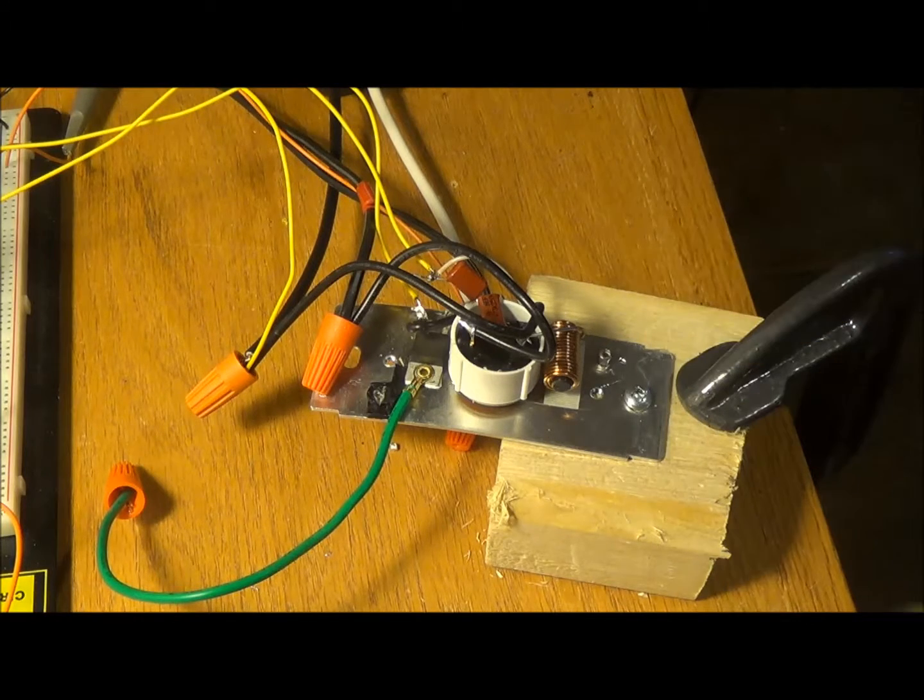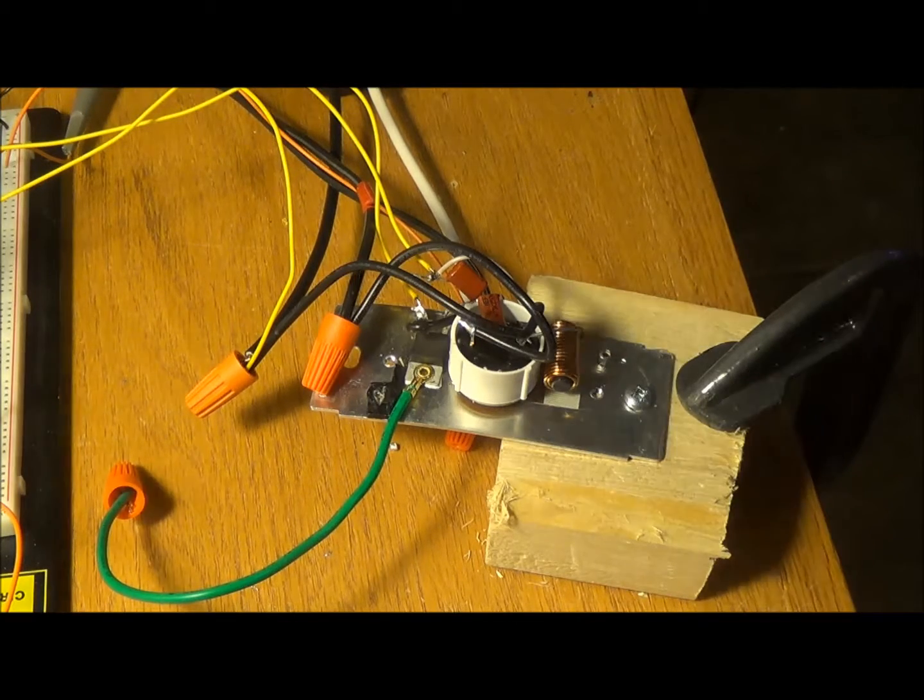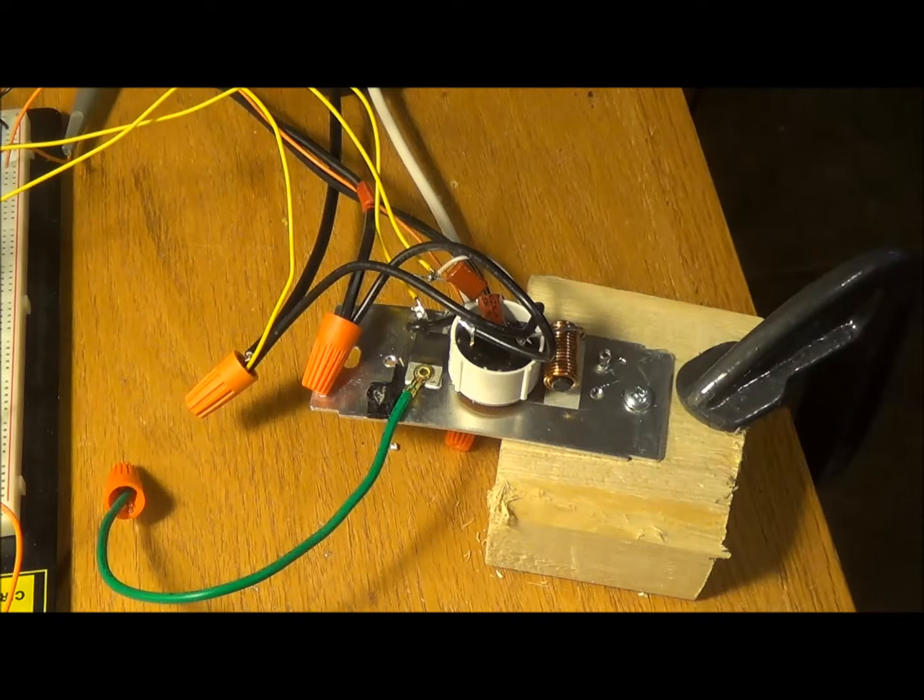The inductor and one of the capacitors are to suppress noise, because as this device goes into conduction and out of conduction, it happens so frequently that it can generate some electrical noise. The other capacitor and the variable resistor are an RC system. It's for timing. It's to determine the conduction angle.